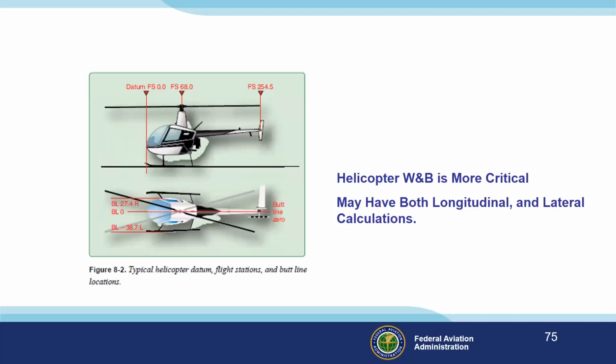Keep in mind that helicopter weight and balance is even more critical than a fixed wing, and most of the time they also have lateral calculations that must be made.